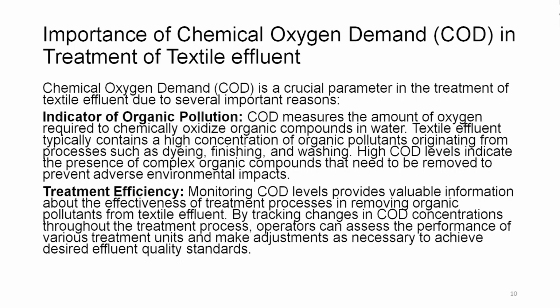Treatment efficiency. Monitoring COD levels provides valuable information about the effectiveness of treatment processes in removing organic pollutants from the textile effluent. By tracking changes in COD concentration throughout the treatment process, operators can assess the performance of various treatment units and make adjustments as necessary to achieve desired effluent quality standards.